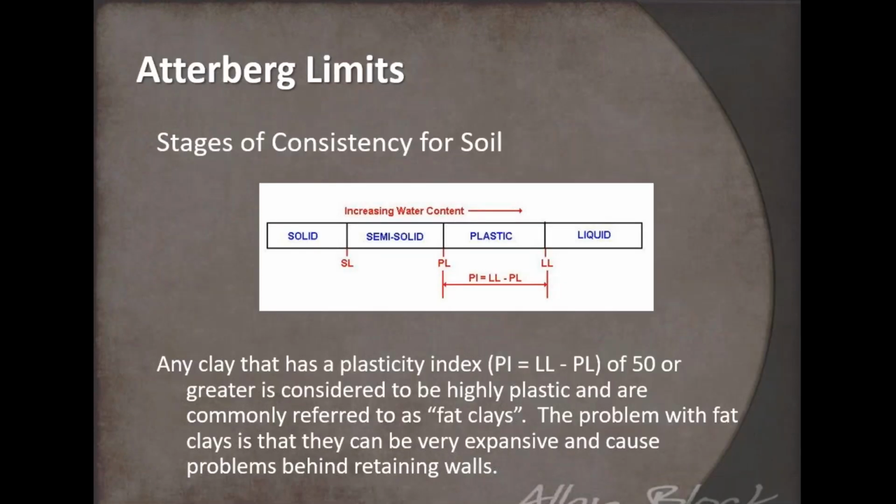But really what we're doing is taking that hard clay, and we know it's kind of a solid, but as we continue to add water, it's going to start behaving less as a solid and a little bit more like a liquid. As we transfer to that plastic state, we get that plastic limit, that PL that's labeled there. Then as we continue to add water, it'll behave a little bit less as a moldable material and a little bit more like a liquid. That's the liquid limit, the threshold we're looking for. So the plasticity index is simply the difference between those two moisture contents.